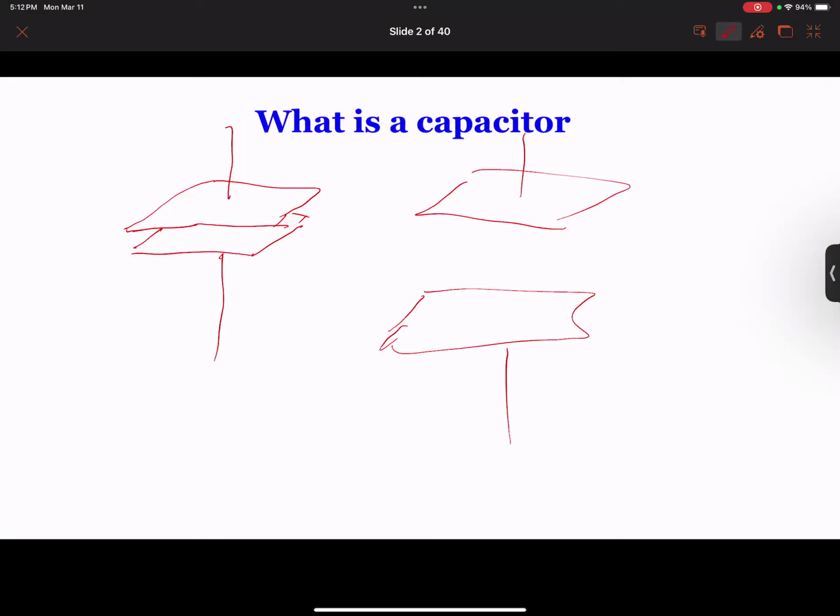The capacitance is there because the gap does not conduct and does not flow current. You cannot have DC current flowing through the capacitor because in the middle there's a barrier, air or something else. So between the two plates, there's no continuous DC current. But when you put a voltage on it, the positive particles accumulate on the positive side, and the electrons accumulate on the other plate.